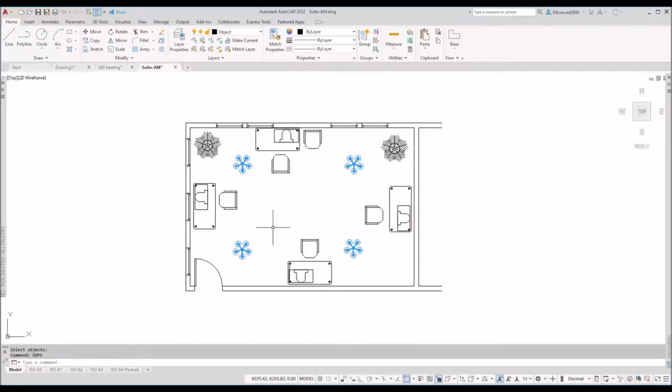Now, that was making the lasso in a clockwise direction. If I make the lasso in an anti-clockwise direction, I get a green lasso, straight off. So it depends whether you go clockwise or anti-clockwise when you're creating the lasso. And again, the space bar will cycle around the options. Okay, so that's the lasso.